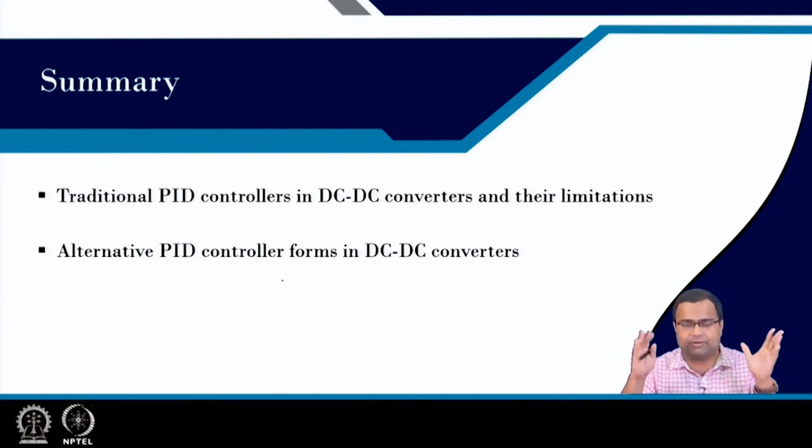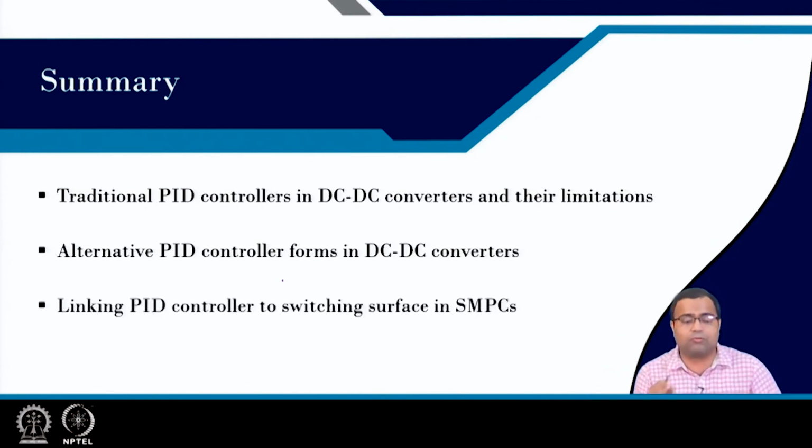So, you have to be very careful, and we should generally use current mode control for the boost converter. And we saw that the current error, inductor minus load current, gives something like a derivative action which is inherently there, and that is why we can think of current mode control with a PI controller, which will look similar to a PID controller, the whole overall system.